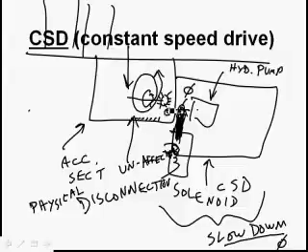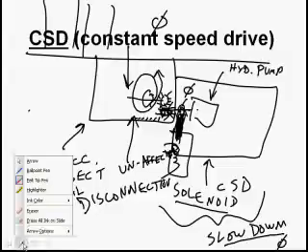And since the gear teeth all got busted off anyway, the constant speed drive isn't going to work. So engineers have rigged it so that even if you flip the switch back to de-energize the solenoid, it still won't go back into the accessory section. You actually have to land the airplane, shut the engine down, wait till the engine has 0 RPM, and you have to open up the cowling, stick a screwdriver in there to push it back and re-engage it, and you cannot do that in flight.